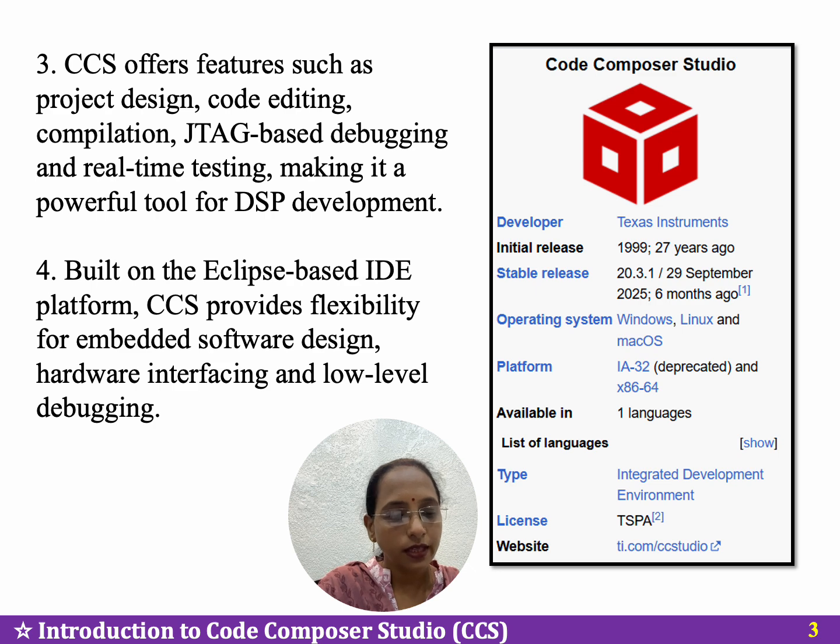CCS overview. In this presentation, the focus is on Code Composer Studio version 12.8.1, which provides an integrated software platform for coding, building, and debugging applications for the Micro DSP 6748 board. It includes an editor, compiler, debugger, target configuration tools, and analysis utilities required for embedded development. The environment supports real-time debugging, project management, and hardware communication through the XDS debug interface.